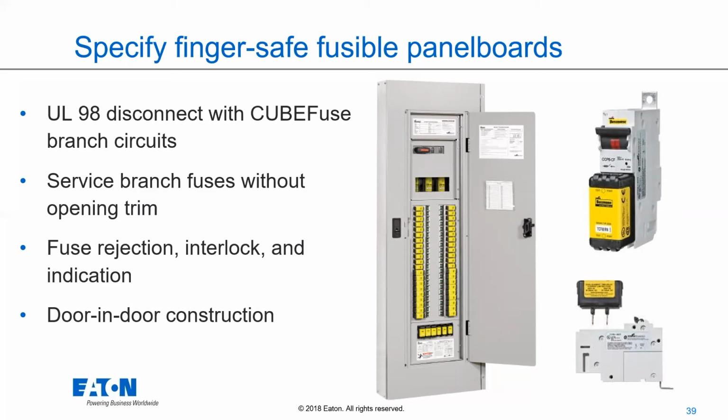I love this finger safe design of this particular product. With this cube fuse, it is finger safe without any additional covers, right? I'm sure we've all seen fuse holders that are finger safe, but there's a cover on them. And the first time you go to take the equipment out, you work on the equipment, you take the covers off, you put them in the bottom of the panel, you toss them, you lose them, and then it comes time to start the equipment back up and you don't reinstall those finger safe covers, right?